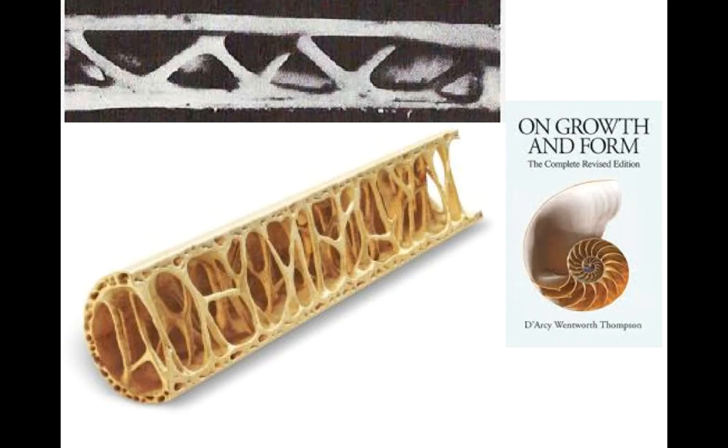We can take those fibers out, redistribute that stress through other fibers in the beam section, and gain a much more efficient section. If you look at, for example, bones in bird wings, where nature is trying to make them as light as possible, you can see this in action. Bird wings have these kind of Warren truss-like diagonals. They have most of their material on the top and bottom, where they'll go into compression and tension, and the wings have eliminated most of the dead weight that is closest to what would be the neutral axis.